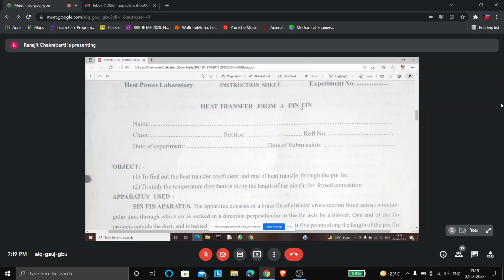So, in order to augment the heat transfer, the easiest way, the cheapest way, is to increase the area of heat transfer. And the fins are actually projected surfaces. So when we have a flat surface between a fluid and its hot body, that is the interface, we want to form projections on that surface.